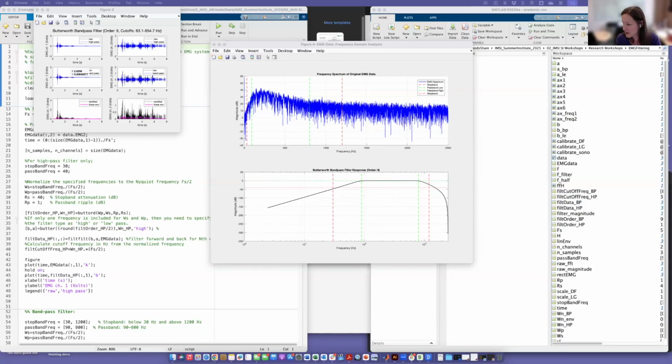Decibels are kind of confusing, but anyway, two signals whose levels differ by 1 decibel have a power ratio of 10 to the 1/10. A change in power by a factor of 10 corresponds to a 10 decibel change in level.